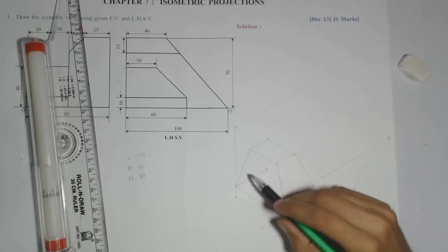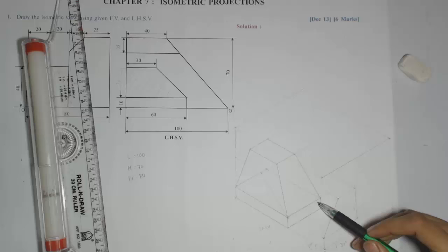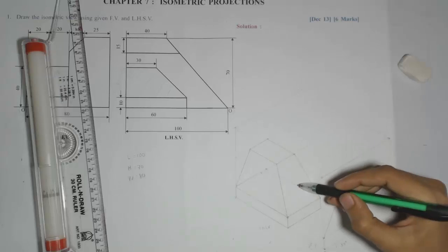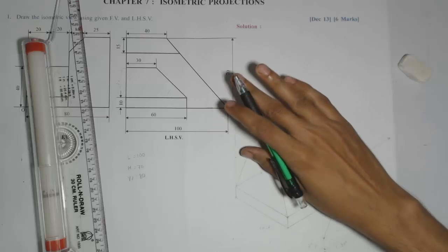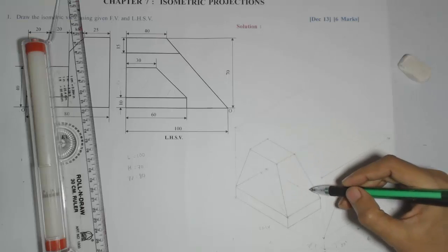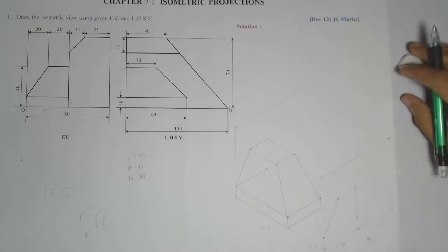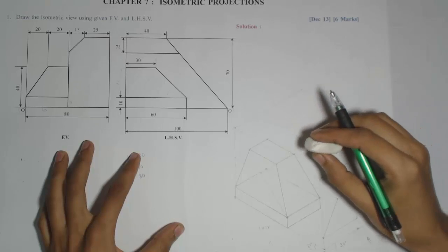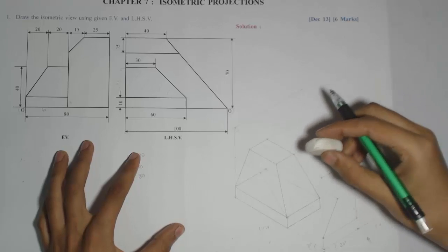Again, the top of that plane, the initial height of 10 mm, which we have drawn like this. Now since this part has come above that top base, these two lines will not be visible to the observer, because they have gone behind this particular plane and this particular plane. So these two lines will not be seen by the observer. That's why I told you initially not to make those lines dark. So now I'll erase everything except the visible parts, because it will create confusion for taking the next heights.